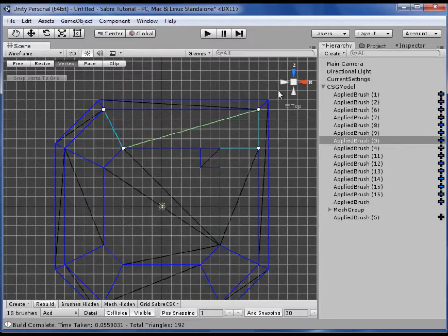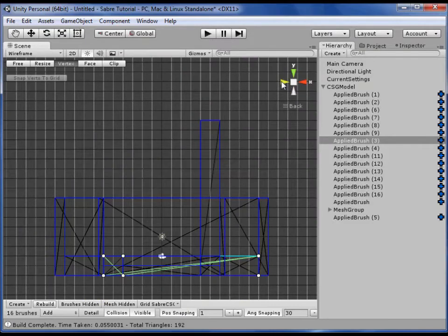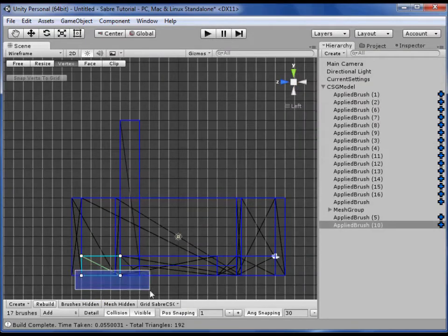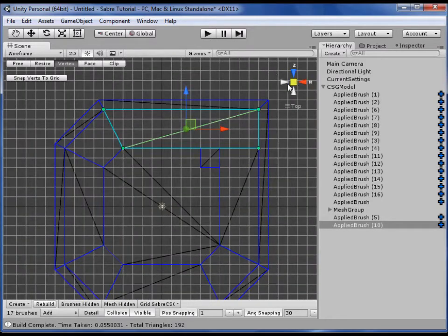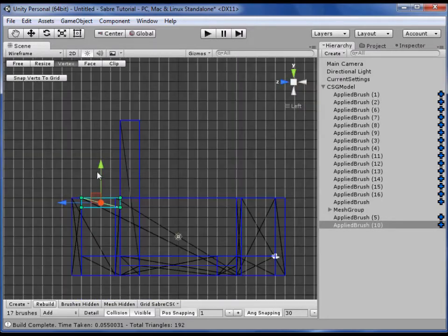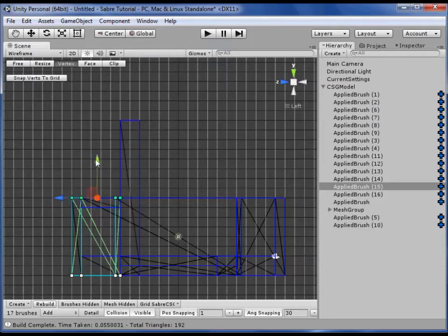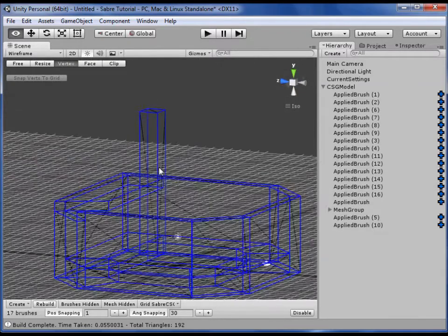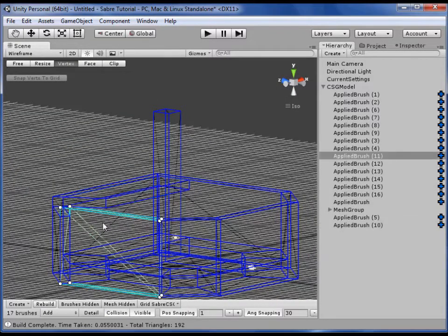Okay, so now let's go ahead and create a start to the second floor. I'm just going to duplicate the floor down here, adjust it slightly, and then bring that up to the floor above. And I'm actually going to lower the walls so that the floor above can rest on top of those walls. And to do that, I'm just going to switch to this perspective briefly.